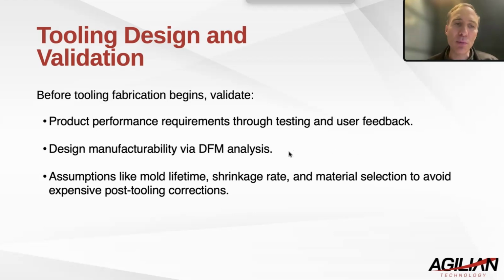This is much better in terms of validation. Design for manufacturability, okay, DFM analysis. Again, the quality of the DFM analysis, including by the tool designer, varies greatly between different plastic suppliers. And you really need to avoid assuming things, get things in writing, right?